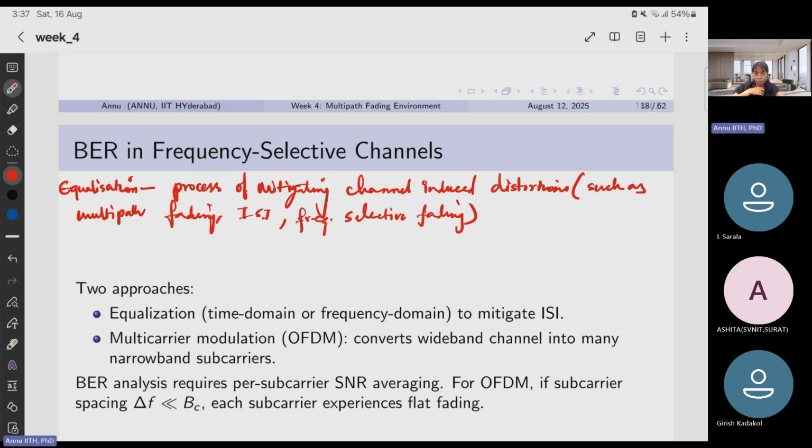They are different. Adaptive equalization uses least mean square and recursive least square. Decision feedback equalization uses previous symbols to cancel ISI. Maximum likelihood uses the Viterbi algorithm to find the most likely transmitted sequence. Linear equalization uses a linear filter to approximate the inverse of the channel. Zero forcing equalization cancels ISI completely but may amplify noise at the same time.